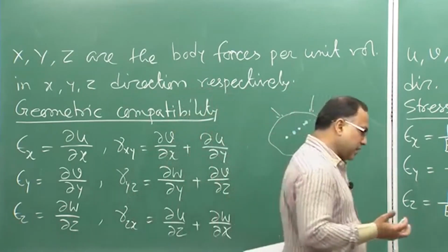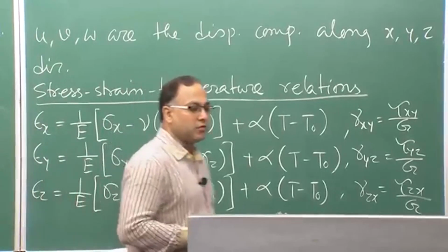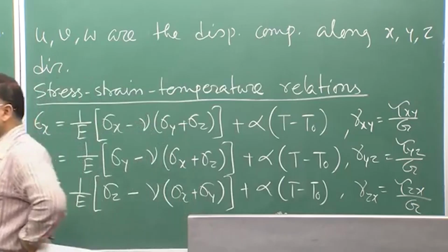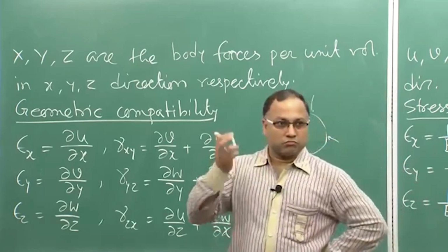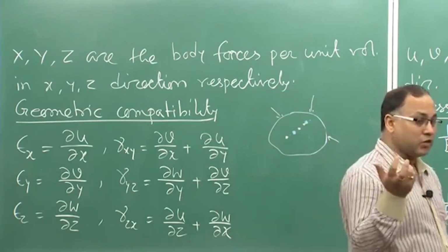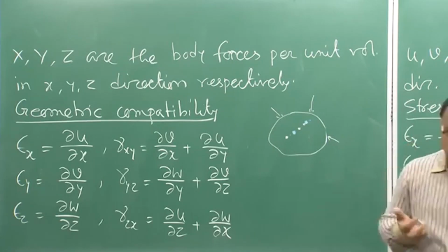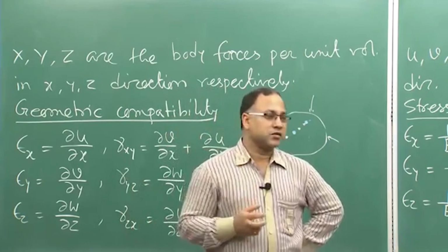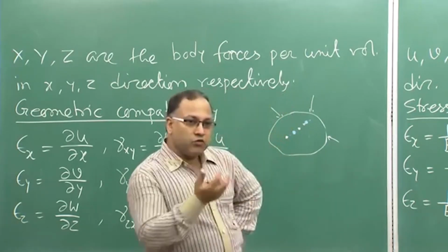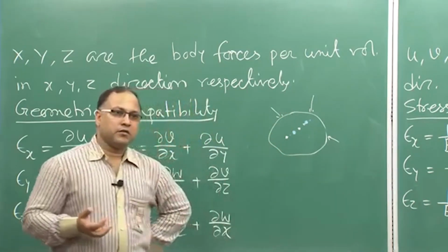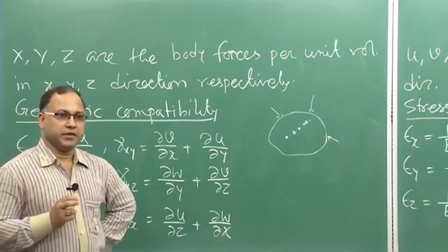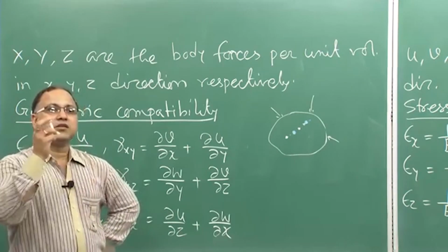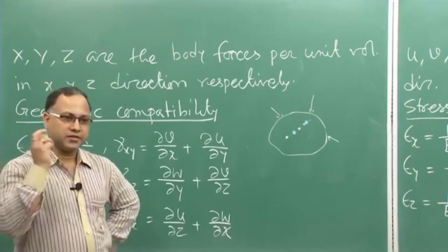This is basically the complete set of equations of elasticity. If you are dealing with theory of elasticity for a system that is non accelerating, isotropic, linear elastic, and with small strain, then these equations must be satisfied, and they will be required to get the complete information about the system.